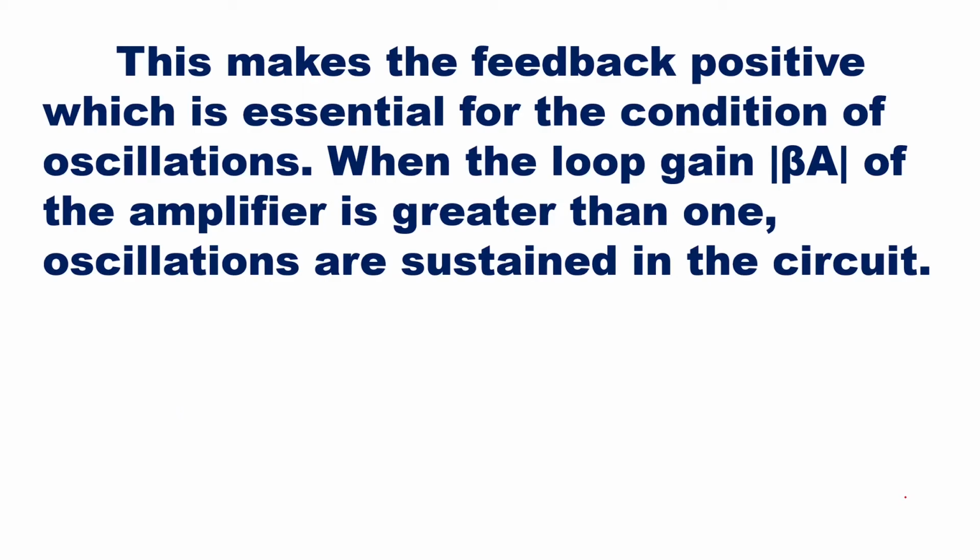This makes the feedback positive, which is essential for the condition of oscillations. When the loop gain, that is the feedback gain into the gain of the amplifier, is greater than 1, oscillations are sustained in the circuit.